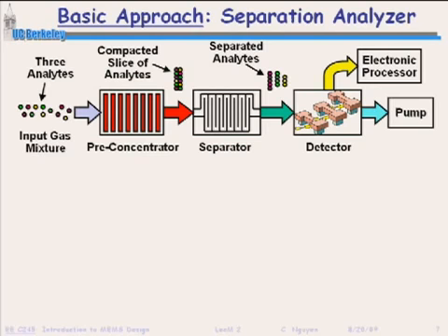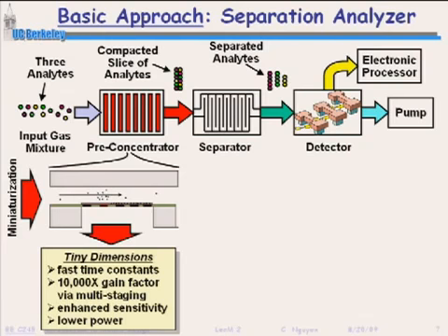So this is an example of a MEMS-based pre-concentrator. It's just a membrane here. It has several pieces of polymer here. And what's happening, these pieces of polymer are so small, it takes very little energy to heat them up to a very hot temperature. And they're also very fast. So what they do is they push out, see, this will push out once, then this will time itself so that when the particles reach there, it pushes out, right? And then so on and so forth.